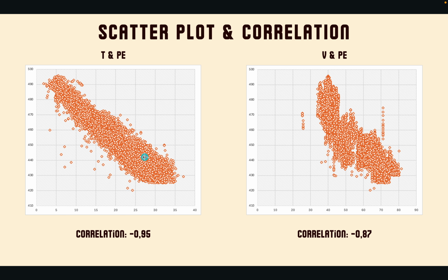This behavior is fully consistent with how the power plant works. In a combined cycle plant, higher air temperature reduces air density at the gas turbine inlet, leading to lower power output. This plot shows that temperature is very important and must be included in the model.